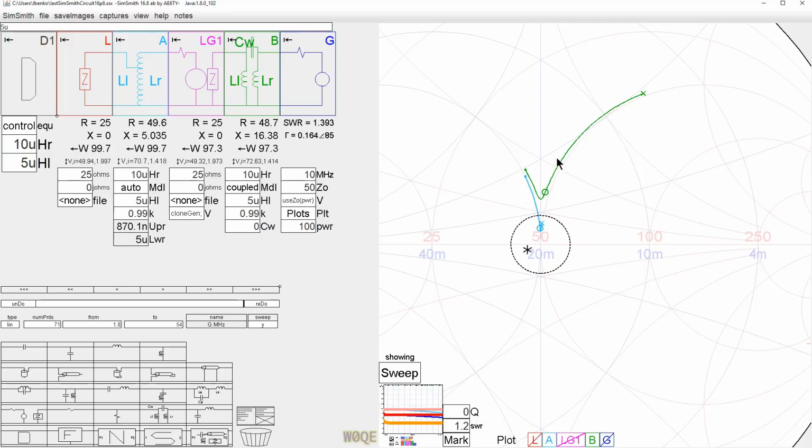The difference between these two is a huge difference. And the huge difference is due to the fact that this 70% of the turns in this winding does not need to have any coupling. It's just current in this winding. It means that if I want to make the performance of the conventional transformer match the performance of the auto transformer, I need to increase the coefficient of coupling some. So let me increase it until they get pretty much the same value. That's very close for the two.